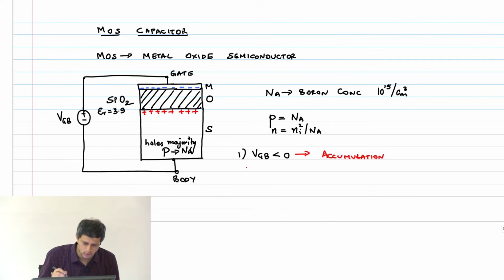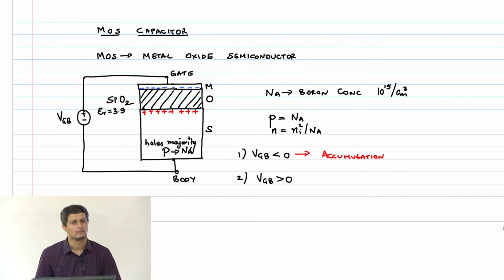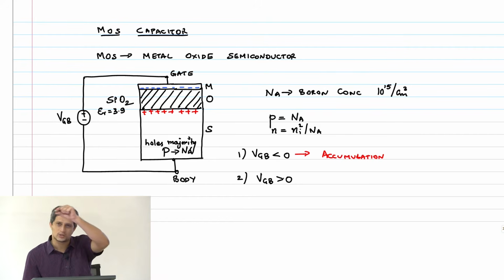Okay, so therefore what you do is you start applying a positive voltage. So now what happens? You start attracting positive charges on that metal gate, because VGB is greater than 0, which means now that I need to attract negative charges.